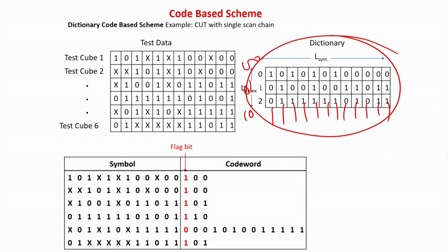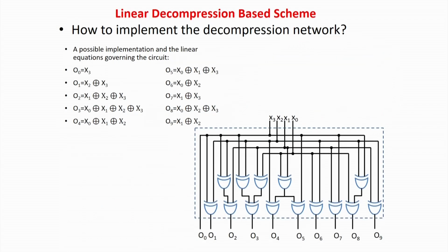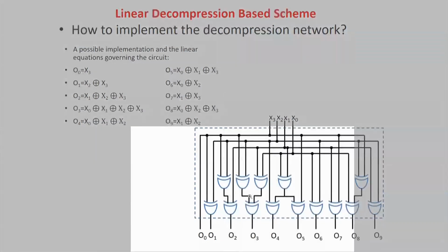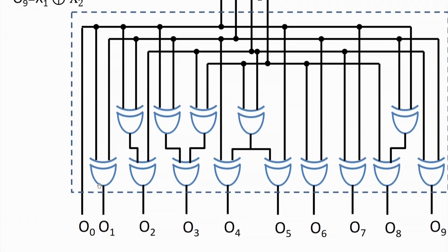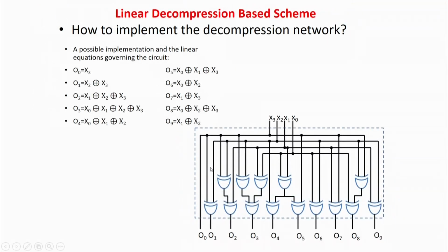Here I will just give you the idea that there are linear circuits, like linear feedback shift registers. Generally there are flip-flops, there are feedbacks, and we have XOR gates in between. And this is a combinational circuit, a slightly simpler version. You can see the input and output are only connected through a chain of series of XOR gates. They are actually called linear operations. When we represent them in matrix terms, we will do it in terms of AND. I will tell you this standard theory.